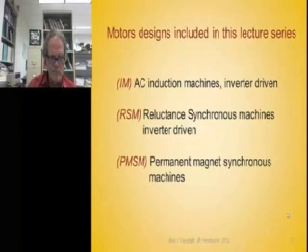And finally, we're going to use the same stator and put a permanent magnet rotor in there to run it as a permanent magnet synchronous machine, and see what we have to do to optimize the rotor to get the best performance. And best performance means the highest torque density at the lowest input power. That's what best performance means: efficiency, power factor, things of that sort.